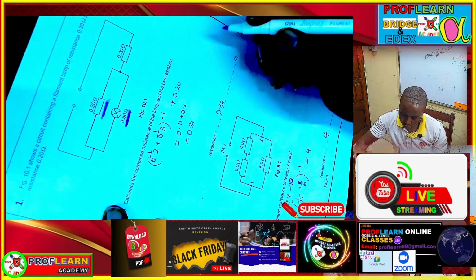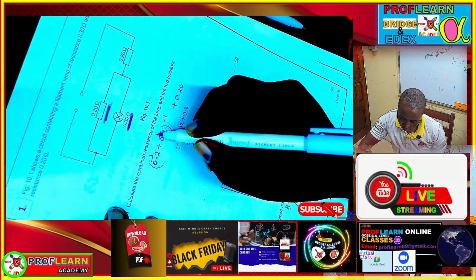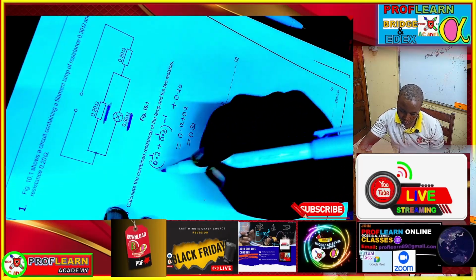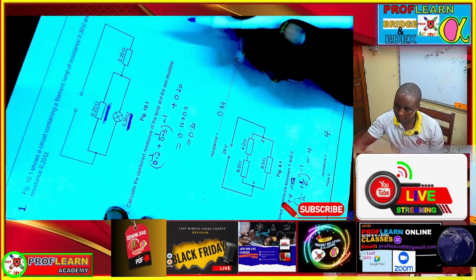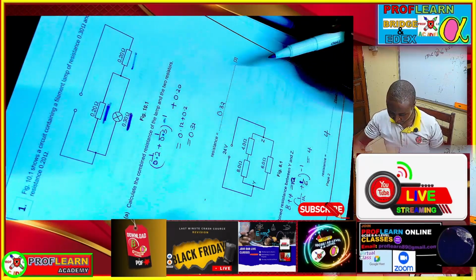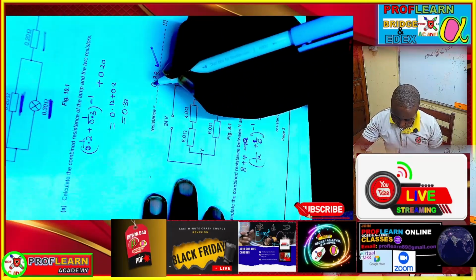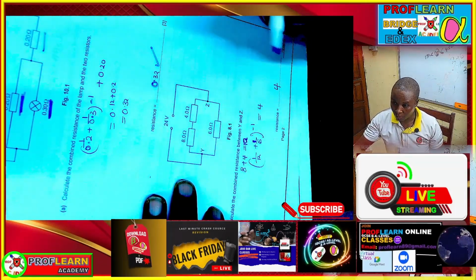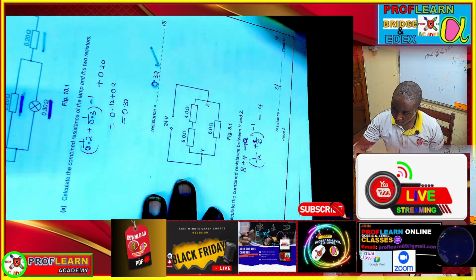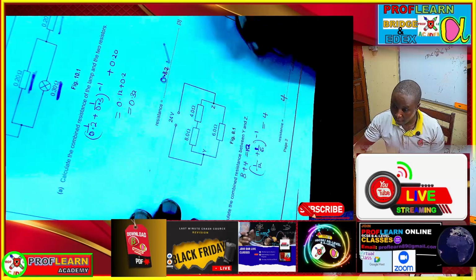So this is the resistor and the lamp. Meaning that for you to work out the combined resistance, it will be 1 over 0.2 plus 1 over 0.3, raised to power negative 1, because these two are in parallel. Then you are going to add this one, which is in series. If you work it out, you're going to get 0.32 as the total combined resistance for this.